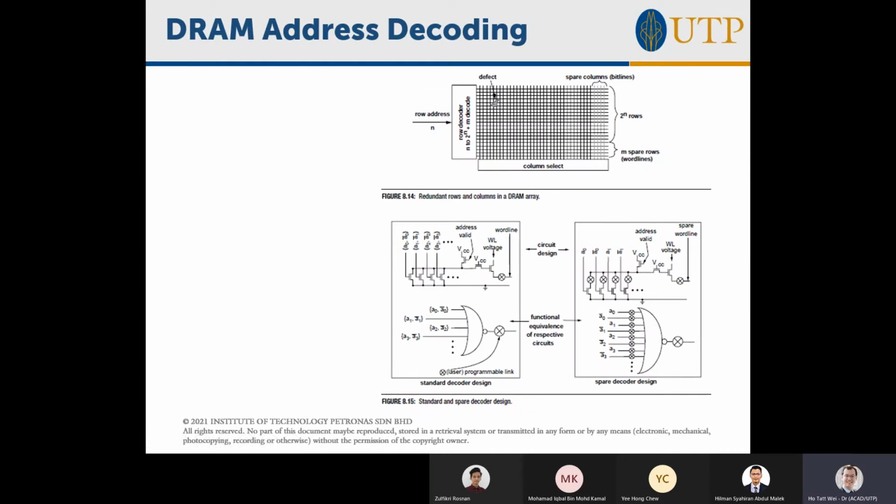And usually you can use a NOR gate or a NAND gate. A NOR gate, if it's all zeros, then it is logic 1, and other than that, it is logic 0. A NAND gate, not AND, if it's 0, 0, 0, 1, 1, 0, it's logic 1, otherwise it's a logic 0. So most likely the decoder usually is made out of NOR gates, because NOR gate will only be 1 if everything is 0, right? So they will choose address or the complement of the address line.